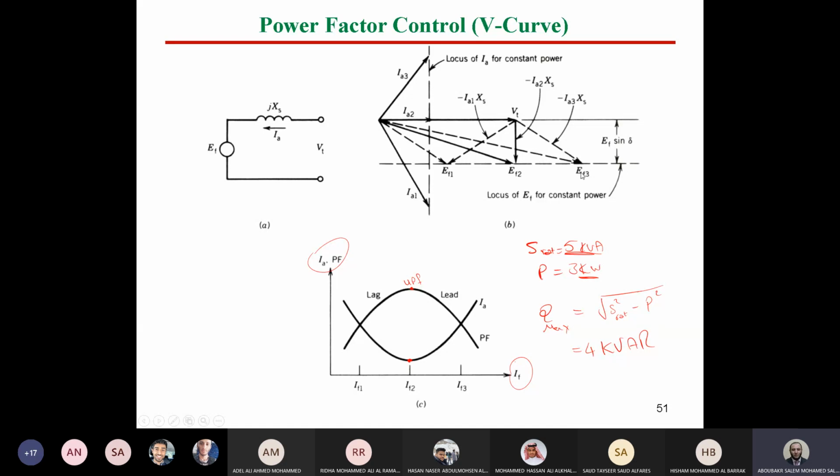Yes. Now, if we assume the operating point for case number 3, if we increase the excitation more, what will happen to the current? It will go increase again and so on, up till making the excitation very high, and even when we remove the load, so delta will be 0. So this is going to make EF in phase with V terminal, right?